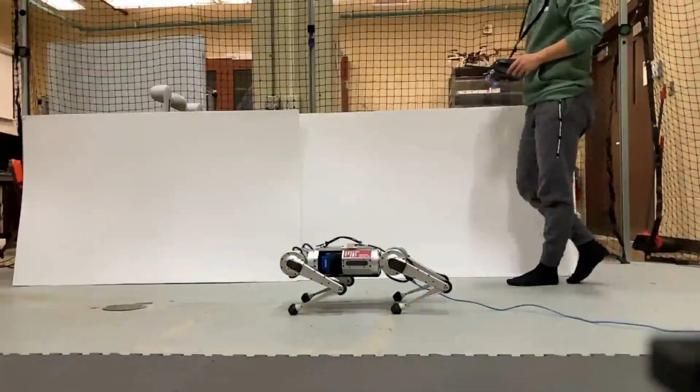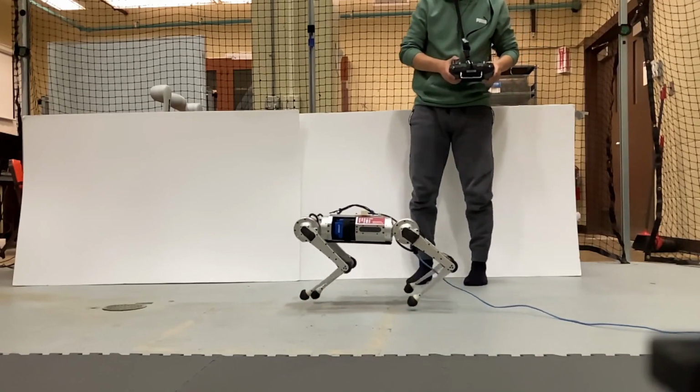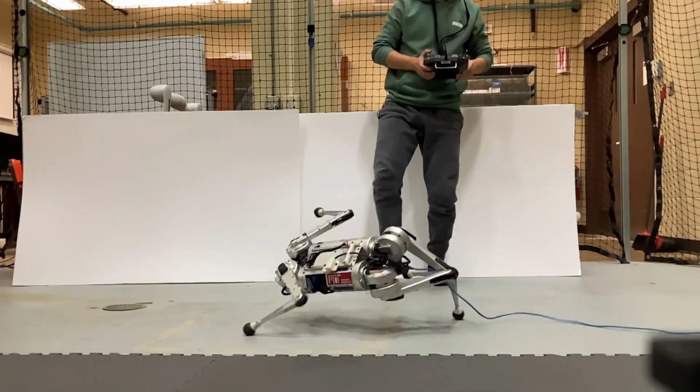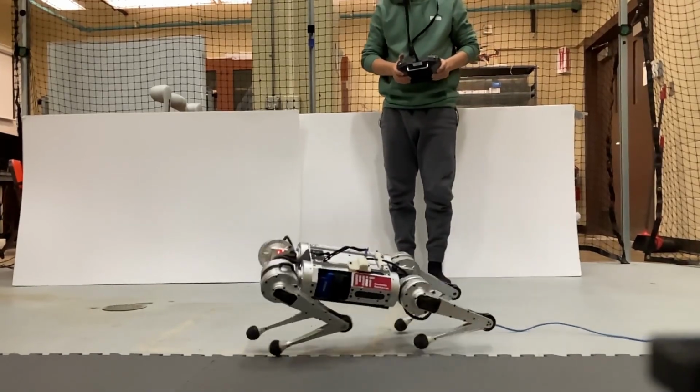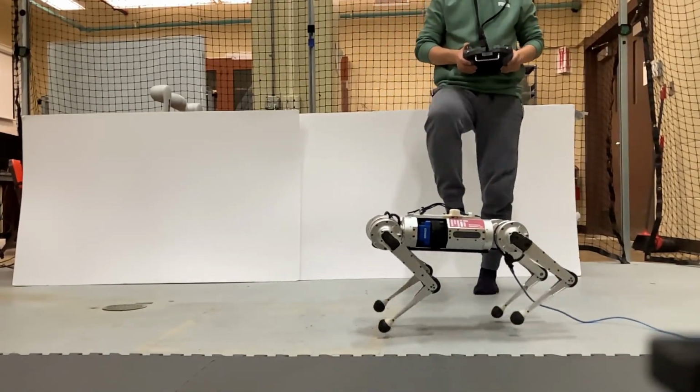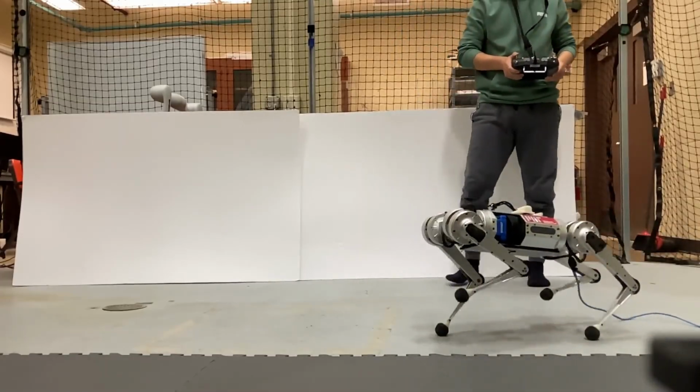Lastly, we pushed the robot very hard to show its disturbance rejection capability on the hardware. In response to the push disturbance, the robot not only placed its stance feet toward the direction of disturbance, but also lifted its swing legs to the opposite direction, which attempted to reorient the body by regulating the angular momentum. This type of reaction is only possible when considering a whole body model and planning.